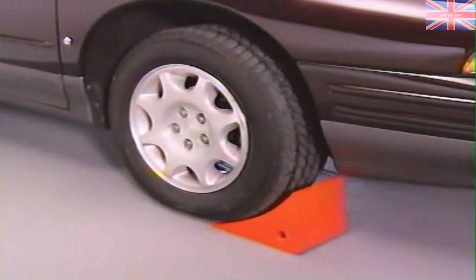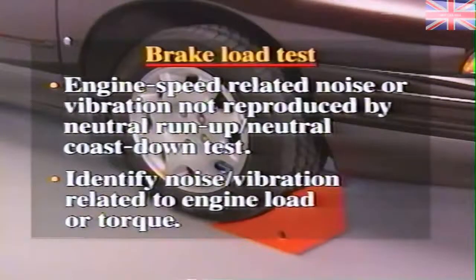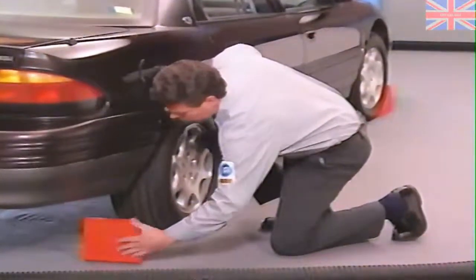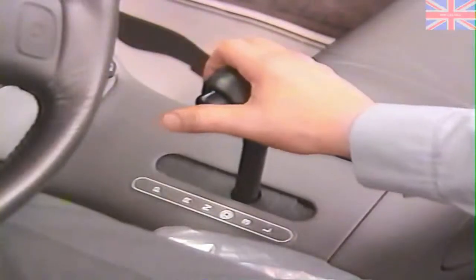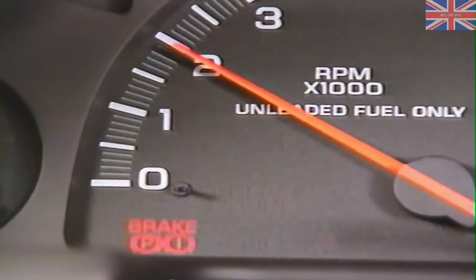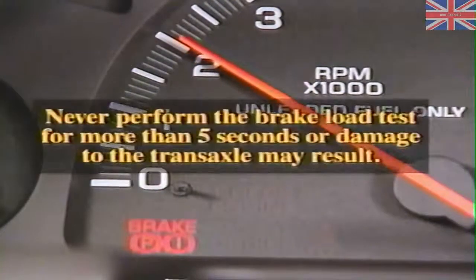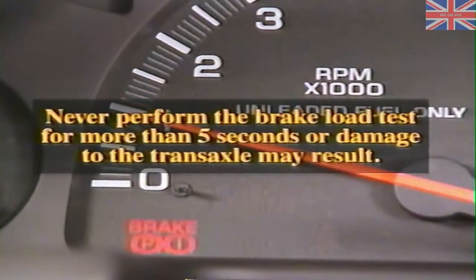The brake load test is designed to identify engine speed-related noise or vibrations that were not reproduced by the neutral run-up test or the neutral coast down test. It also works for noise and vibrations that are sensitive to engine load or torque. Block the front and back wheels. Apply both the parking brake and the service brake. Then place the vehicle in drive. Increase the engine RPM looking for vibrations that match the customer's description. Never perform the brake load test for more than 5 seconds or damage to the transaxle may result.